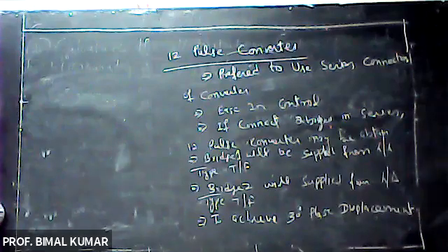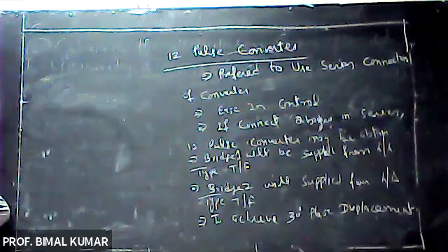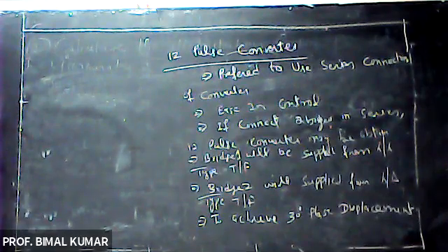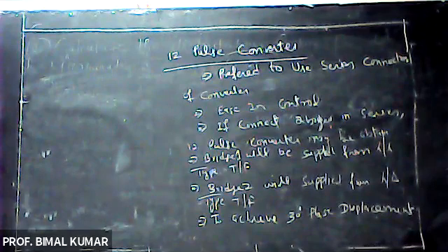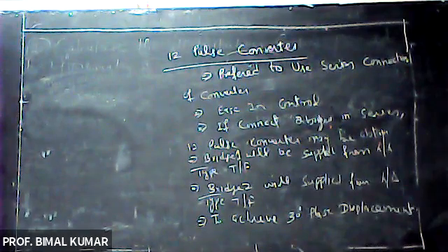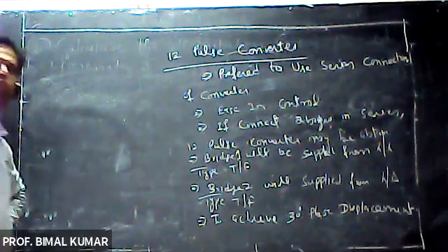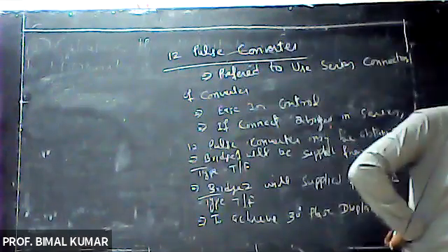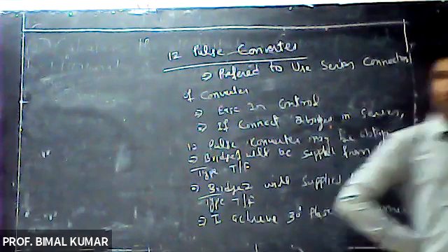So bridge 1 is supplied from transformer 1, and that is of star type. Bridge 1 is connected with star type transformer. Bridge 2 is connected with star delta type transformer. Why is it so? Because if we are using this type of transformer connection, we will be able to get 30-degree phase displacement, which is required for 12 pulse converter.